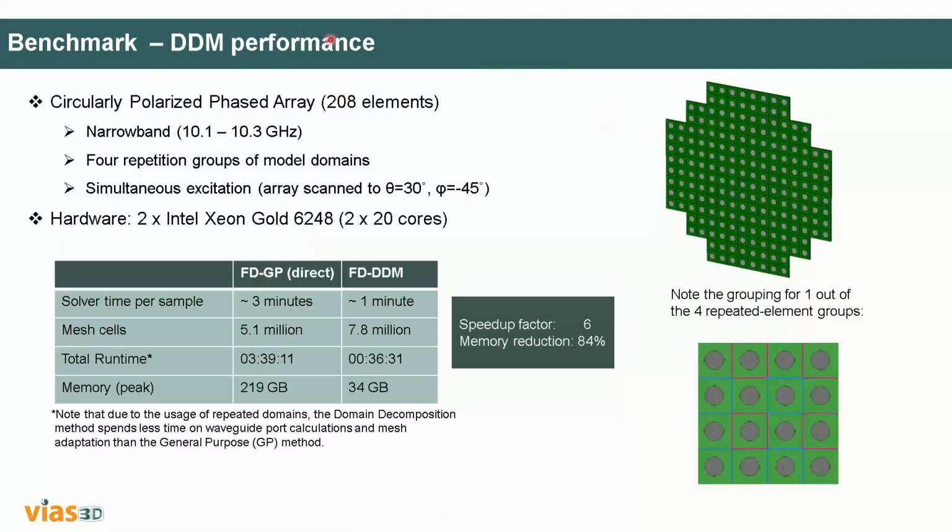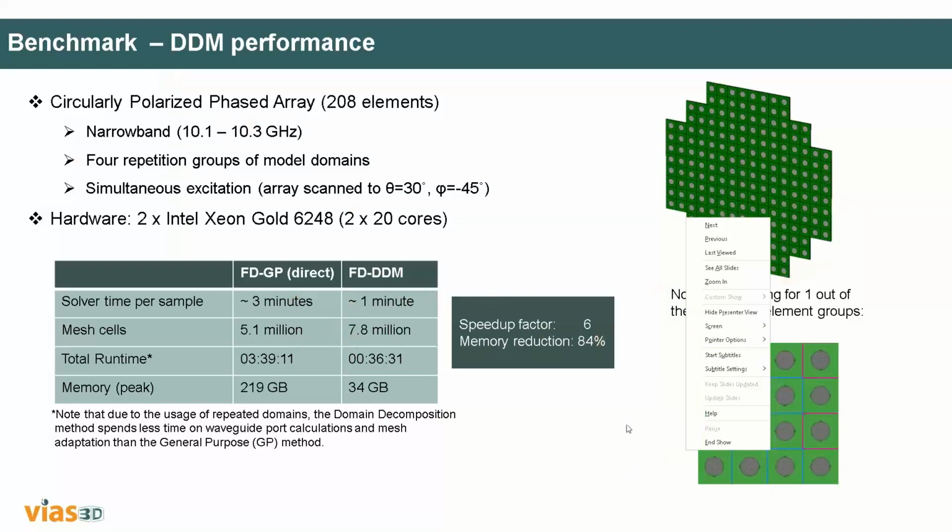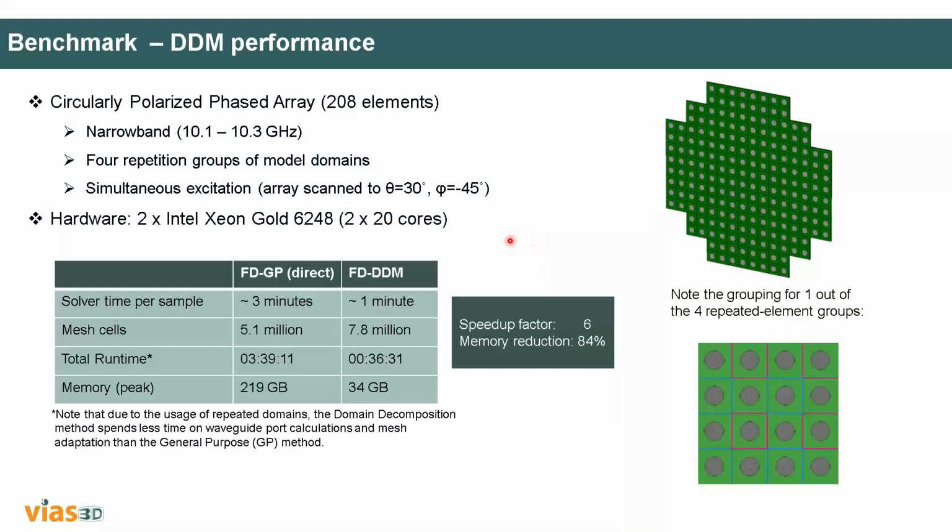The reason we are using this method is that, as I told you, an antenna array is best simulated using the time domain solver, but unfortunately certain highly resonating structures will not give you the best result, or the best time, in time domain solvers, because certain antennas are best suited for the frequency domain because of their highly resonating nature. So we have to use the frequency domain solver, even though it will take a lot of time and memory. But using the DDM approach, that is a recent addition to the different kinds of antenna array methods.